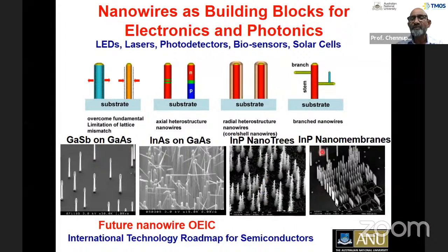And most recently we are moving from nanowires to nanomembranes, because this opens up a lot of opportunities. Most importantly, the International Technology Roadmap for Semiconductors, the group setting what technologies are needed for electronics, has identified nanowires as a key technology component for next generation electronics. That's why IBM Zurich and others have major research programs on integration of III-V semiconductors and silicon, where lattice mismatch is no longer an issue. They've already demonstrated indium gallium arsenide based vertical transistors on 6-inch silicon wafers or so. It's a really exciting development in terms of using nanowires for a wide variety of applications.